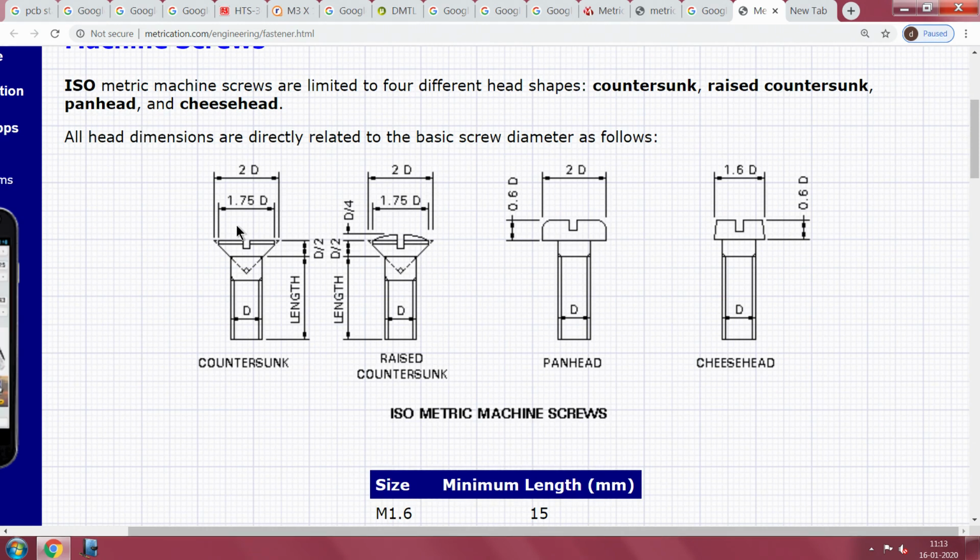Typically in small workshops, where the drilling is perfectly done, countersunk to tapped hole, there is no issue at all. You understand, countersunk to tapped hole, there is no issue at all in case it is done perfectly. But you will notice that this countersunk locates the thing perfectly. Once you call this an M3 countersunk screw, the diameter of 2D, the diameter of 1.75 and the angle of 45 degrees are fixed. So, when a screw sits in that, it sits without the slightest chance for error.